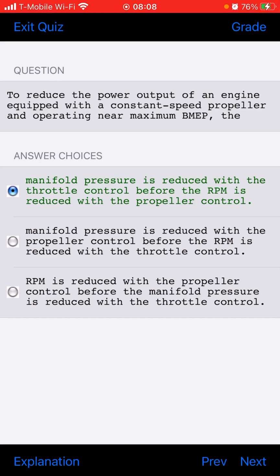Direct mechanical push-pull carburetor heat control linkages should normally be adjusted so that the stop located on the diverter valve will be contacted.